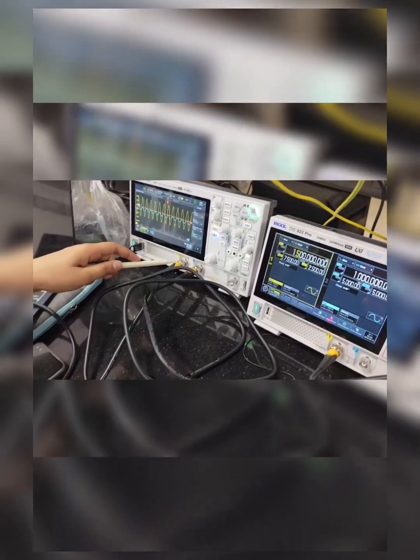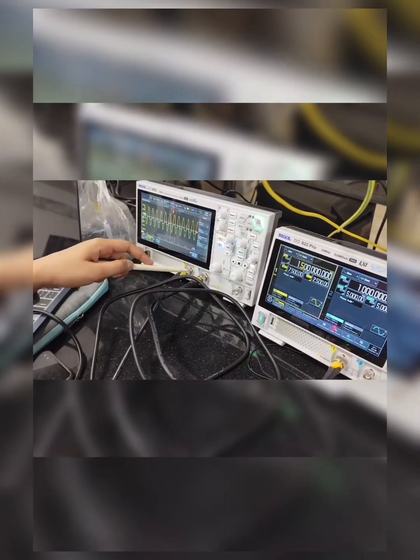Here, I connected the signal generator to the LED and I also connected it to the oscilloscope so we can get the waveform of the input. Now, here I placed the photodiode in front of the LED and I provided a 5 volt DC source using Arduino. And I also connected the oscilloscope across the resistor to get the output waveform. Here, in channel 1 I connected the input source and in channel 2 I connected the output source.